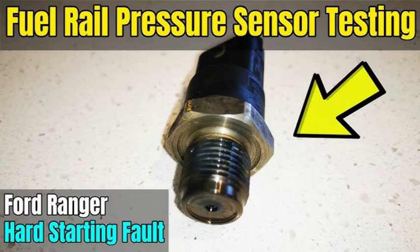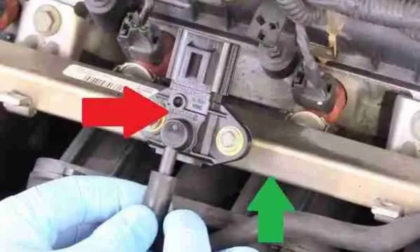Clogged fuel filter. A clogged fuel filter can restrict fuel flow to the fuel rail, which can cause the P0191 code. Fuel pump problems. A weak or failing fuel pump can also cause the P0191 code. The fuel pump is responsible for supplying fuel to the engine, and if it is not working properly, it can cause the fuel pressure to drop. Electrical problems. Electrical problems such as a faulty wiring harness or a loose connection can also cause the P0191 code.